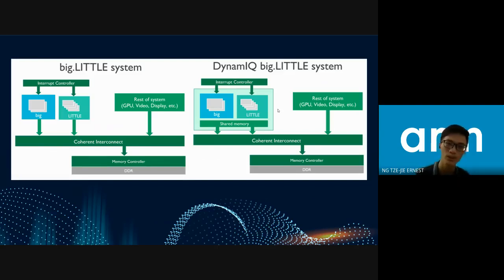This technology offers a wider range of possible configurations or combinations of big and little cores to meet the unique needs of an application. On the new DynamIQ multiprocessor design, each core will have a private L2 cache and a shared L3 cache for every cluster, delivering higher performance, efficiency, and the possibility of optimizing the design.